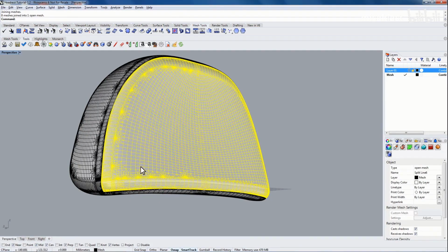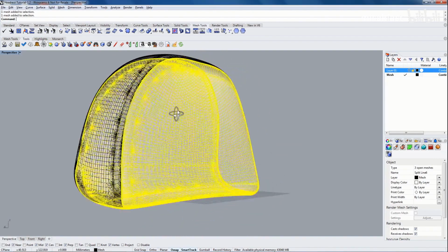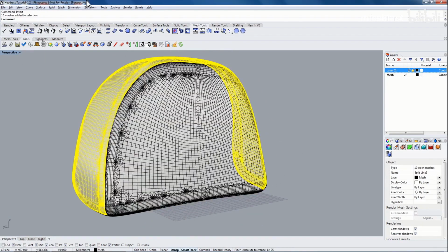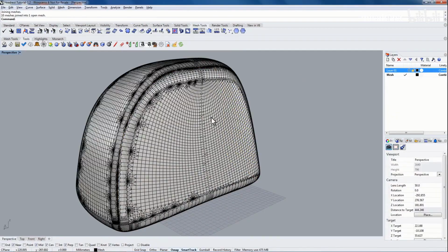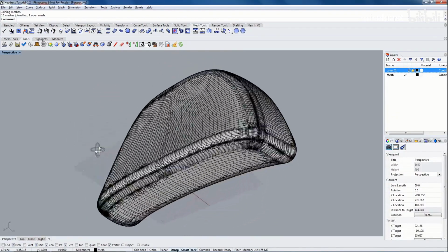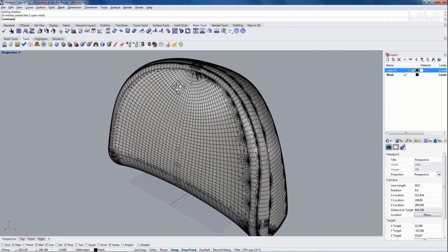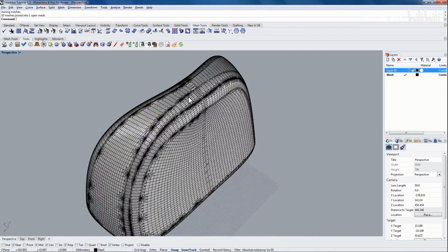For the last piece, instead of selecting all the faces, I'm going to select the 3 faces that I have already joined. Now I'm going to type invert into the command line to invert my selection. And now I can type in join to join these faces together. By joining these faces together, we have created a single mesh that is comprised of many different sub-meshes.